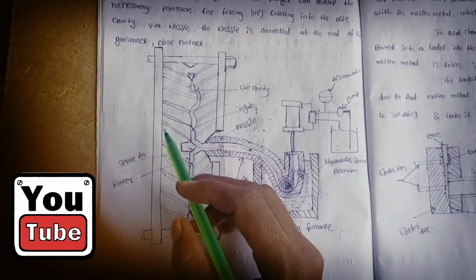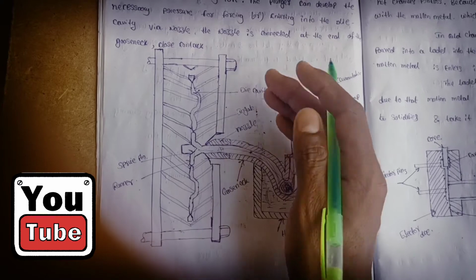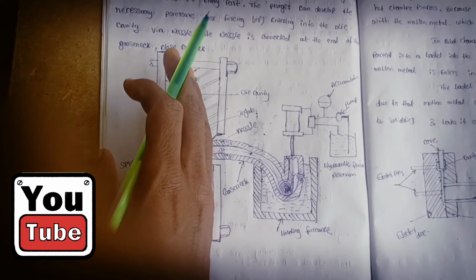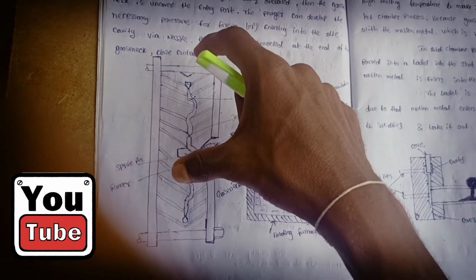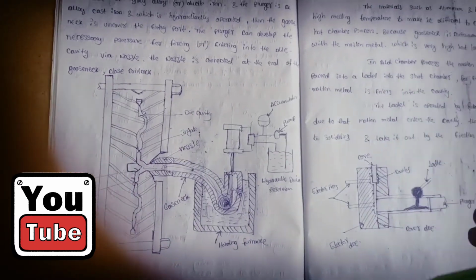Here there is an ejector plate. One is a movable part, the other one is a fixed part. So this is the fixed part, this is the movable part. This part is connected to the ejector pins. That means it can be moved, and it can take the component outside by these ejector pins, and we can take the mold cavity's required shape out by these ejector pins.